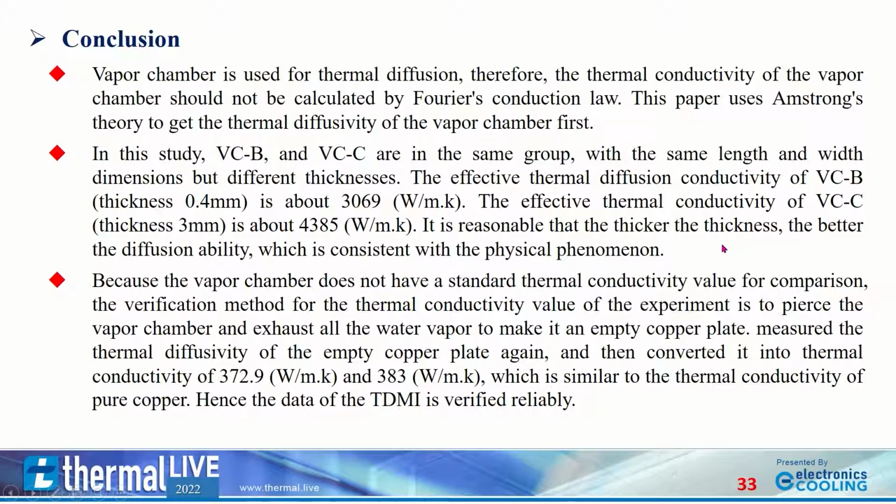Because the vapor chamber does not have a standard thermal conductivity value for comparison, the verification method for the experimental thermal conductivity values is to pierce the vapor chamber and exhaust all the water vapor to make it an empty copper plate.